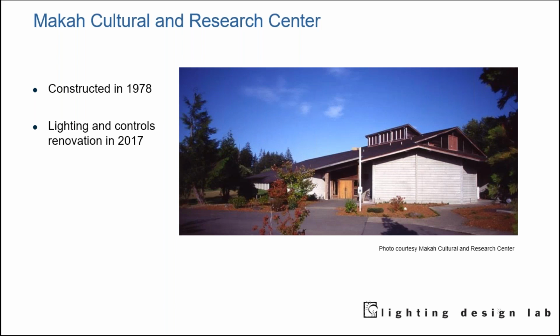The lamps were various arrays of PAR lamps and reflector lamps of varying wattages, whatever was available in town. Each display case had its own dimmer, and the open areas were controlled with large wattage incandescent dimmers overridden by circuit breakers. No time clocks, just circuit breakers.